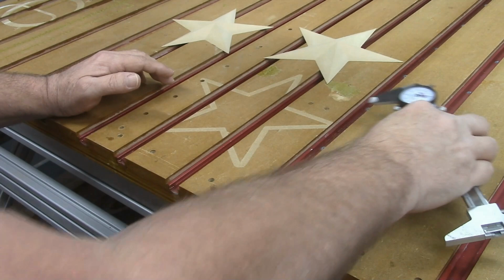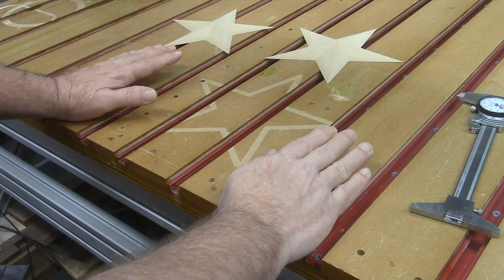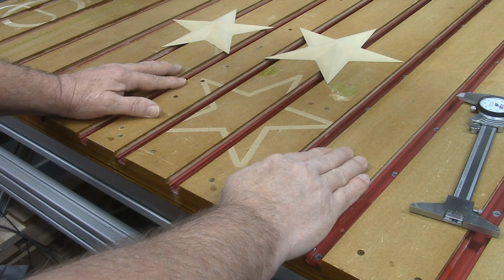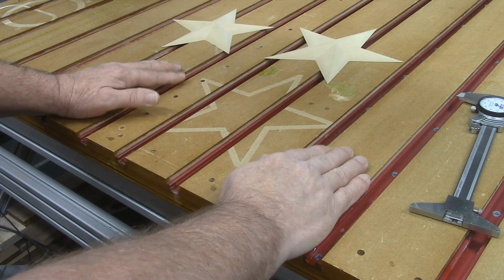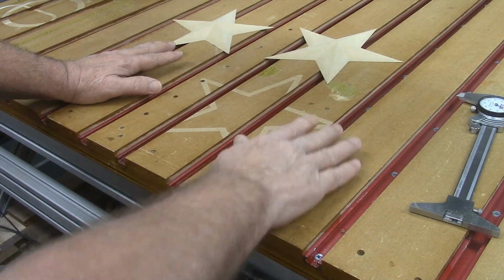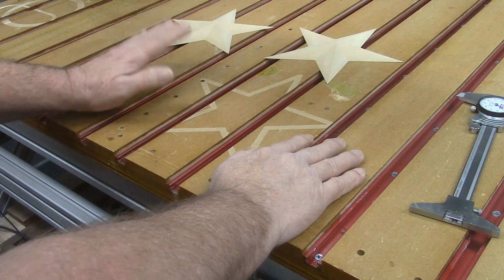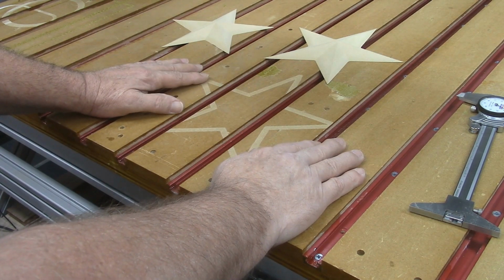So what happened? Well, what happened was an oversight on my part. It came down to two words: axis calibration. After getting my Avid CNC built, in my excitement to start using it, I never calibrated my X, Y, or Z axis.